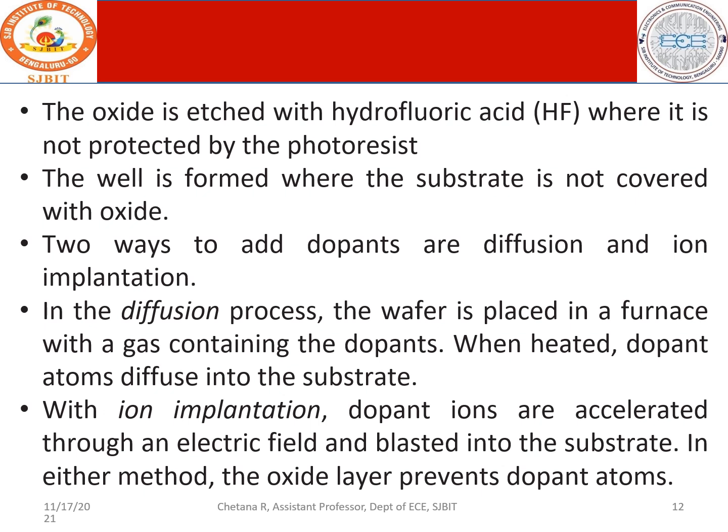In either method, the oxide layer prevents the dopant atoms from entering. I told you, apart from the oxide layer, you also have a masking. So in either case, it is possible for us to do the doping. Expenditure is also a factor. Diffusion consumes comparatively less expenditure than ion implantation. So this is the procedure involved in doing the necessary dopings. The two procedures are diffusion and ion implantation.